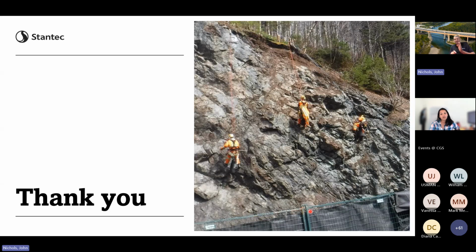So it's basically saying, when you're not in line with the discontinuity, then rock mass conditions apply. But as soon as that failure surface comes into an area of that discontinuity, then you can apply the strength parameters based on the discontinuity strength.